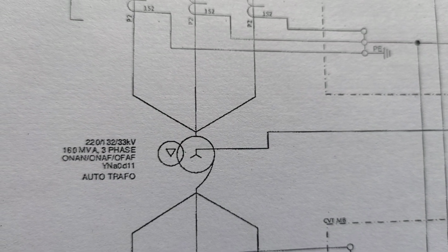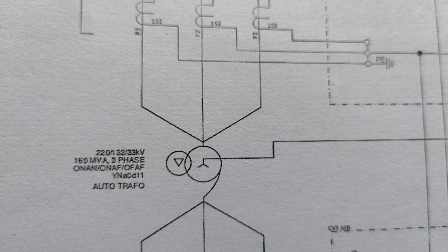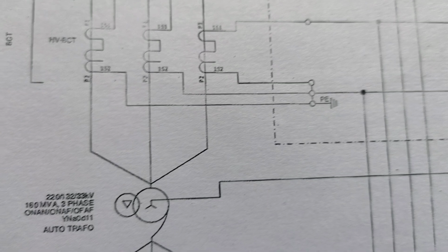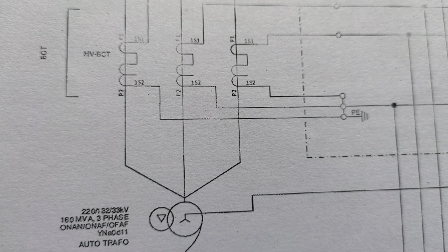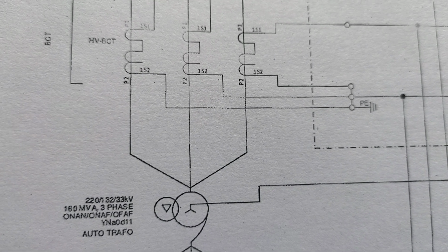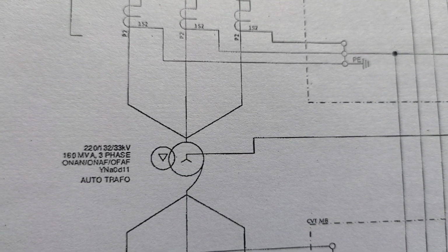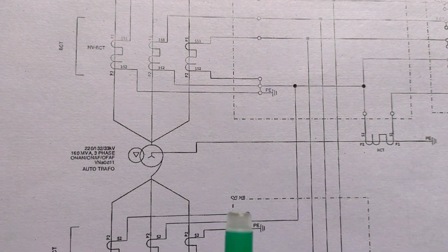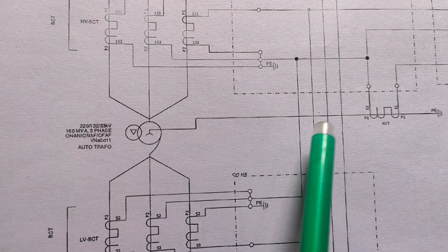So today our discussion topic is related to the REF connections and how the REF functions for the transformers. The name of the protection is REF. So what is the full form of REF? REF full form is restricted earth fault. That means the fault is restricted to some zone. So what is the restricted zone here? The restricted zone is in between the transformer's primary and secondary winding and its neutral.